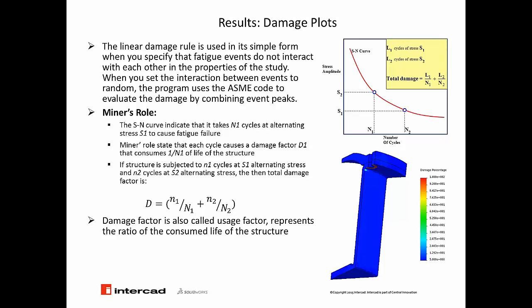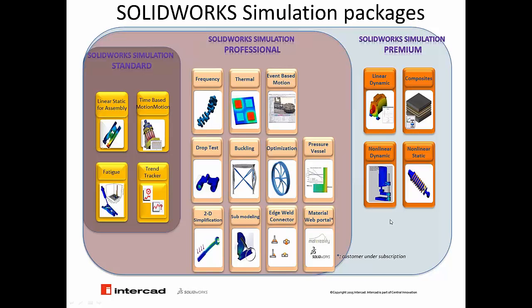In fatigue studies we are simply calling them either as a ratio of that load or cycle peaks of these loads, then applying them to our model and looking at the damage factor and how much life simply remains in the structure. All this said here is a part of SolidWorks Simulation Standard.